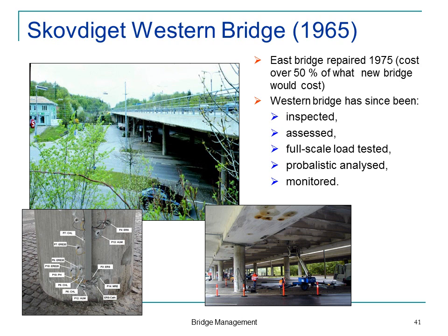And I would say, ever since then we inspected the access, and we have even done full-scale load testing on it. Full-scale load testing is essentially very simple. If the structure had to be able to carry a load of so and so many tons, then you place so and so many tons on the bridge, and well, it didn't collapse. Fine, safety is okay. Of course, we do it a bit more detailed, and we put the load on gradually. But we did that a couple of times.